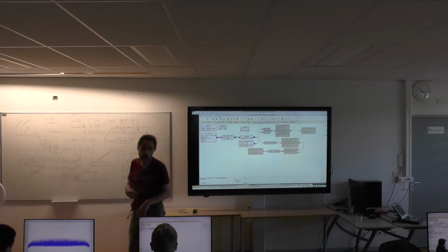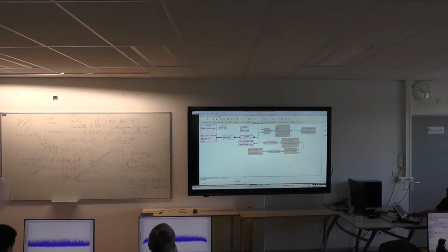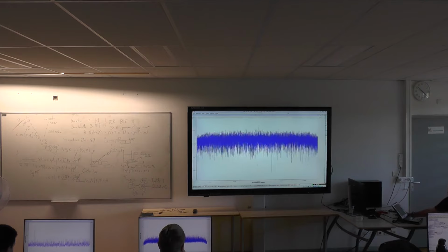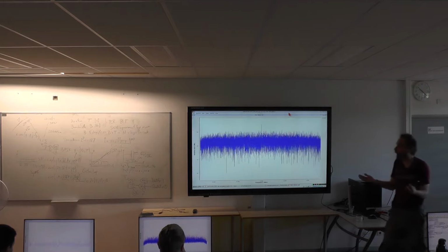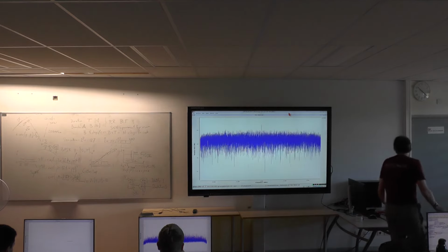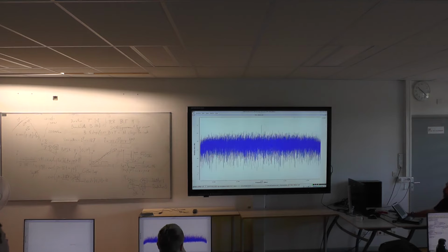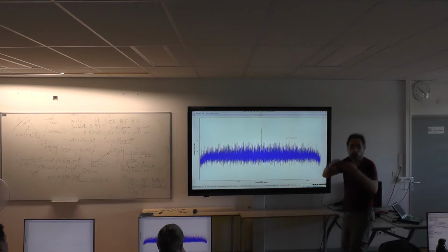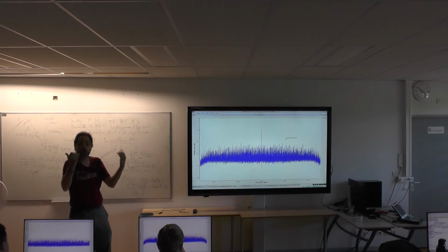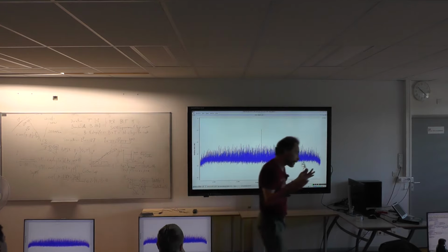And the first thing we can do is look at the spectrum. What is the spectrum of a GPS signal? So I loaded the data, I run this, and what you see here is nothing. There's nothing to be seen. I tried to tell you GPS is 10 to 20 dB below thermal noise. So all we're sampling here is noise. And actually, if you click on the middle button and you run an averaging, you can average as much as you want. You spread the information over 2 megahertz, and the spread information due to BPSK is well below thermal noise. So you will have a very hard time getting the GPS signal out of the noise.